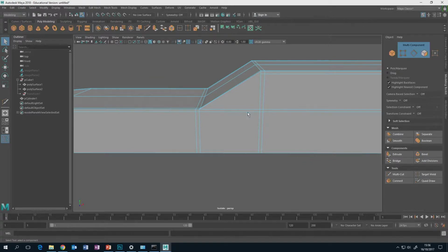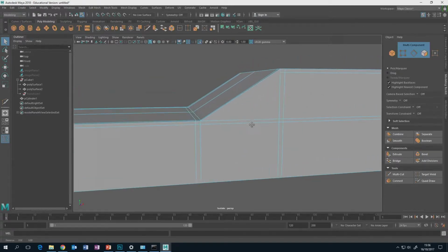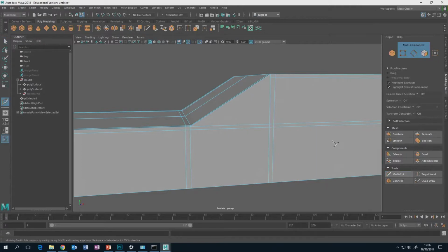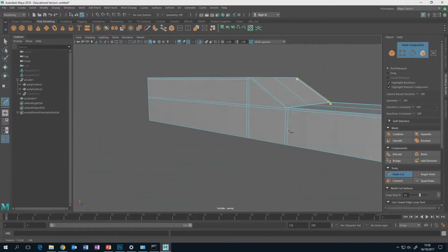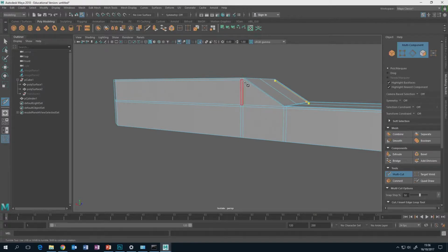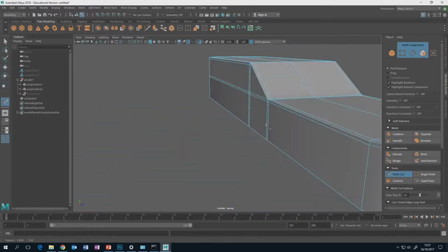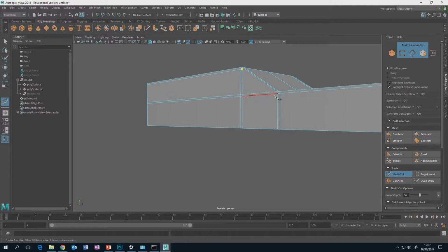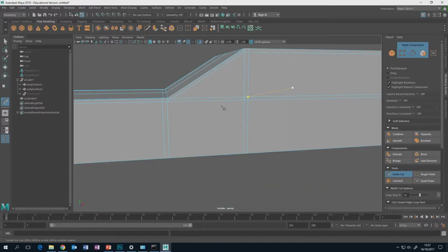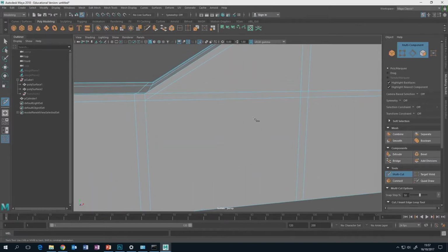and maybe we can connect up some points, because where at all possible we want to have it so we're just dealing with polygons that have 4 sides if possible. So we're using a multicut to connect. Oops. I needed to press return on that to say yes, that's where I want it. And one down here. Yeah, that's where I want it. We might need to delete some edges here as well.